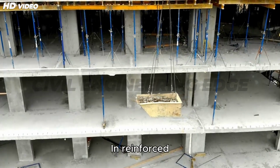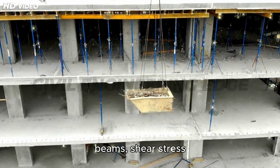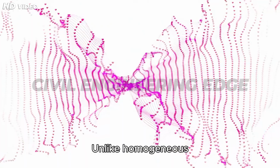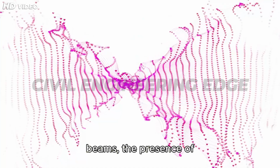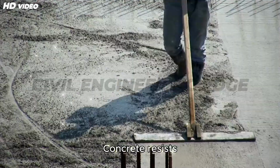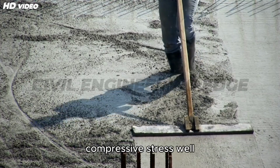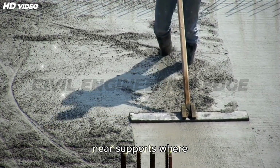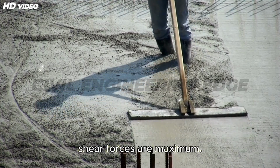What are shear stresses in RC beams? In reinforced concrete RC beams, shear stress develops due to vertical or inclined loads. Unlike homogeneous beams, the presence of reinforcement alters the stress distribution. Concrete resists compressive stress well, but is weak in tension and shear, especially near supports where shear forces are maximum.